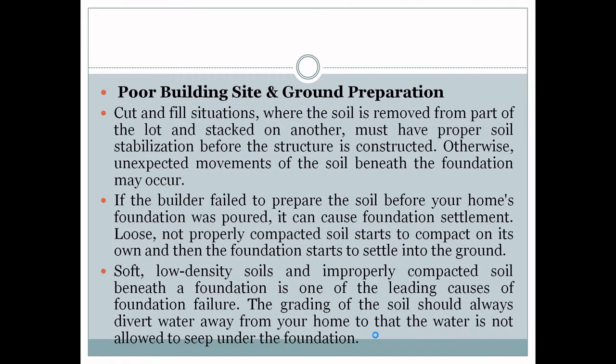Next, poor building site and ground preparation. In a cutting and filling situation, where the soil is removed from part of the lot and stacked on another, there must be proper soil stabilization before the structure is constructed. Otherwise, unexpected movement of the soil beneath the foundation may occur. If the builder failed to prepare the soil before your home foundation was poured, it can cause foundation settlement.